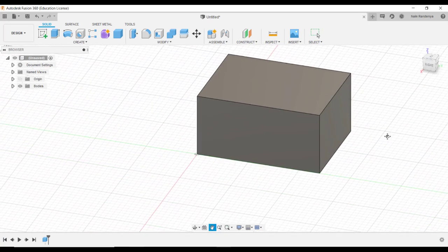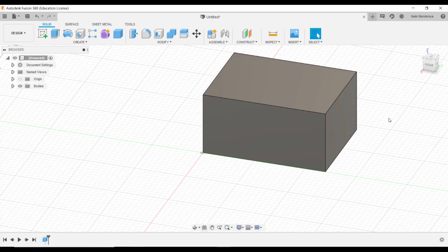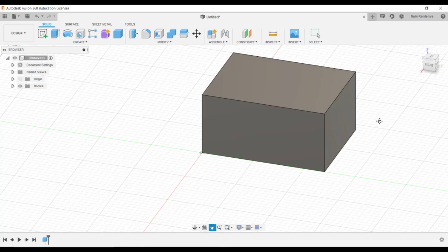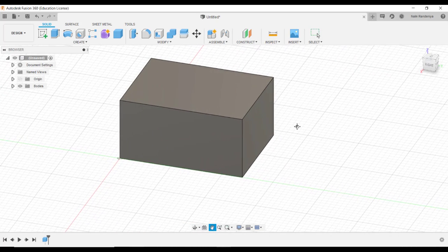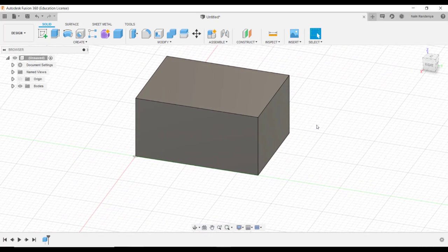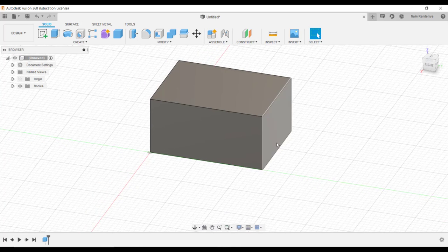Okay. Since we have something on the workspace now, let me show you the mouse operations. I'm doing this operation, and we call this panning. Panning is done by pressing and holding the middle mouse button, which is the roller. Most computer mice these days have this button. Otherwise, in this navigation toolbar you have a button called pan, and when you press that, you can also do the panning.